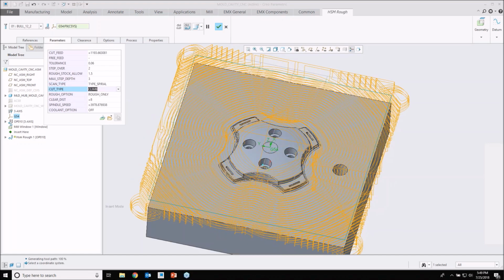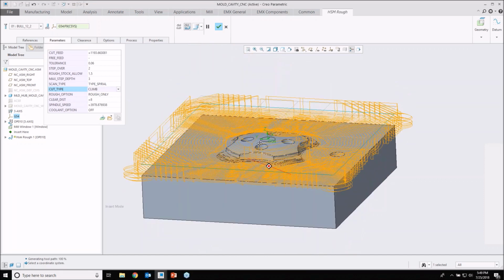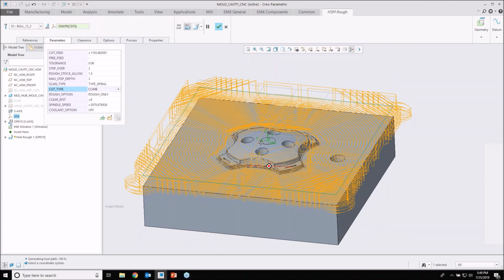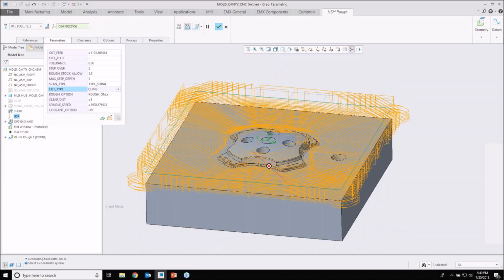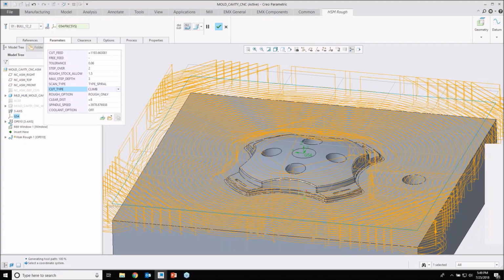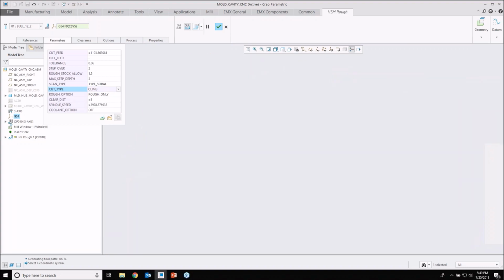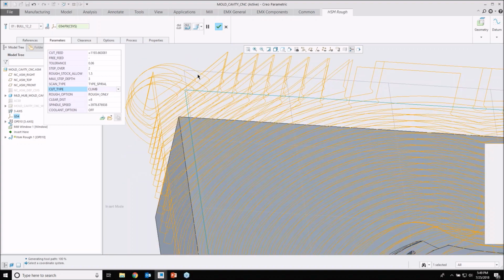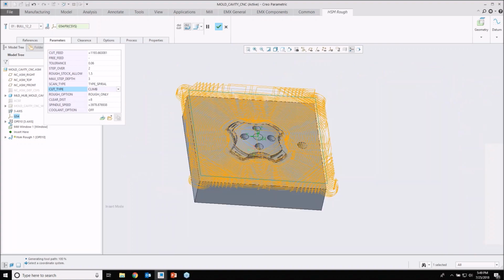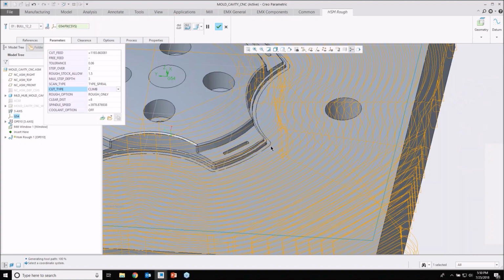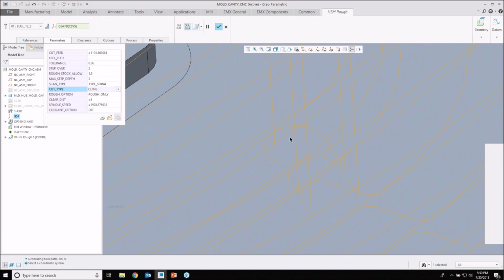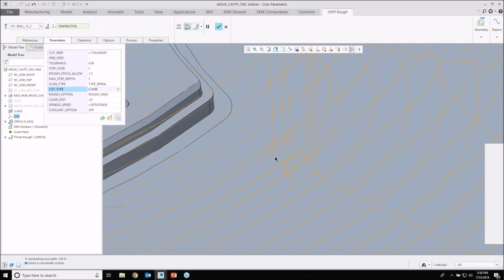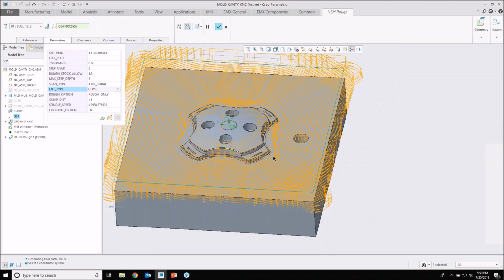So you'll notice also how quickly I can go through these options and how quickly Creo will give me some feedback on that. So also it's a little bit better in the middle. I'm still having a lot of ups and downs over here, but you can still see I don't have any sharp corners. So as it's entering the job and as it's cutting, it's trying to move away from those sharp corners, which is basically what you want when you're doing high speed milling.